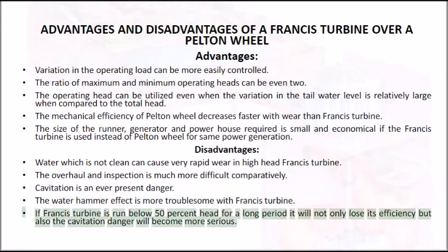If a Francis turbine is run below 50% head for a long period, it will not only lose its efficiency but also the cavitation danger will become more serious.